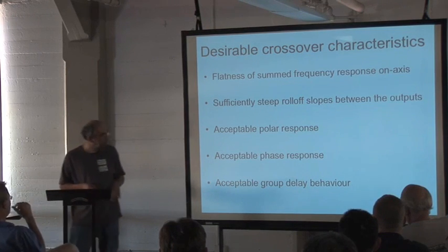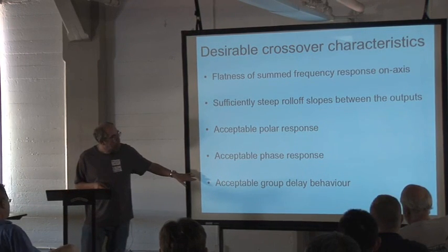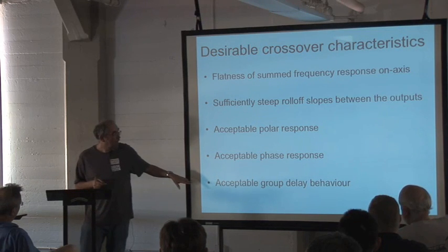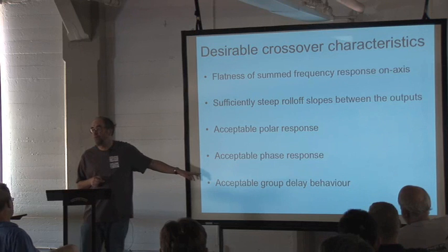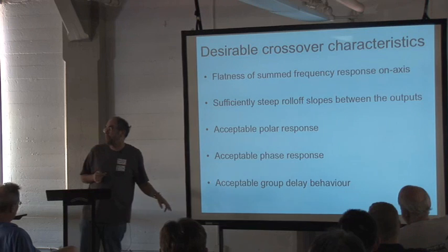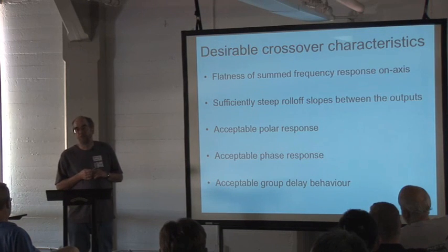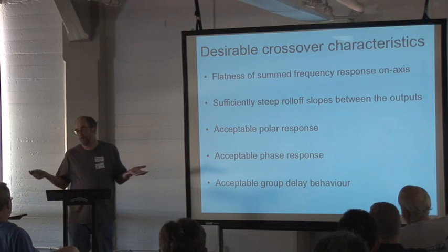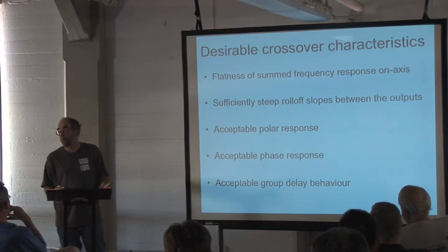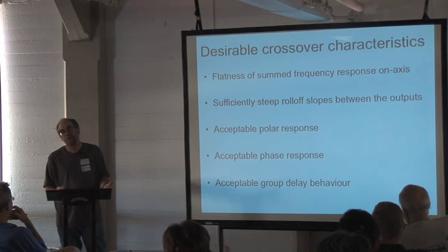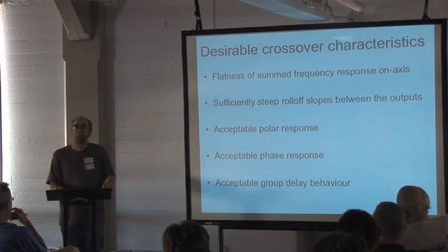Very much tied up with that is the group delay behavior. So, in other words, some frequencies are going to be delayed more than others because of the phase response. Once again, is that a problem? And the answer, once again, from experiments seems to be it's not until it becomes gross. All of the figures on what you can hear tend to come from years ago from telephone systems, whereas what was acceptable as a group delay problem over a long telephone line. And the same kind of thresholds do seem to obtain in hi-fi, because the human ear is still working the same way. Anyway, next slide.